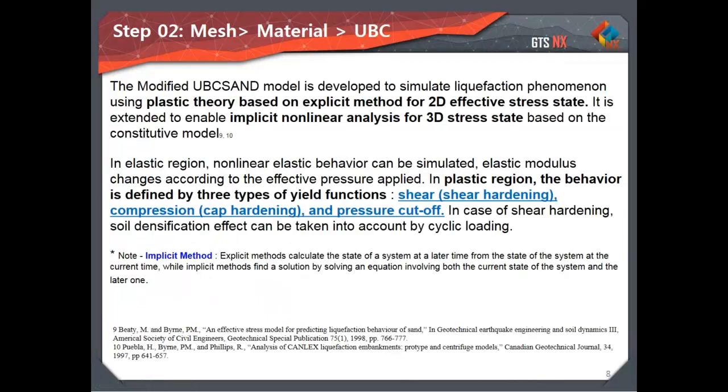So a quick overview of this constitutive model. It was developed to simulate the liquefaction phenomenon. It's a plastic theory based on an explicit method for 2D effective stress state, and then it's extended by the implicit nonlinear method for 3D. So the elastic behavior is basically nonlinear elastic behavior captured by the elastic modulus.